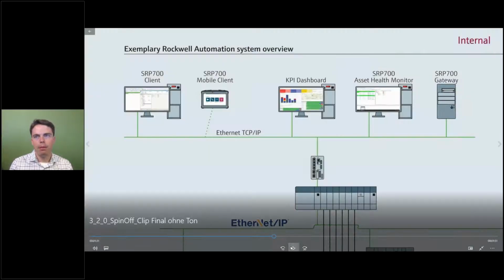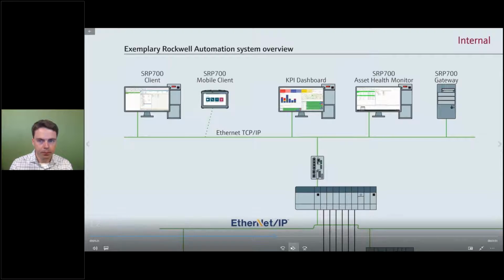The whole system is capable of handling up to 10,000 tags. Every gateway machine handles around 500 to 1,000 tags. It depends on how many tags are monitored, at what frequency, and on the hardware and software capability of that gateway. So it's really easily scalable. It works for small installations. We have a very attractive offering for small sites with 100 tags, really up to 5,000 or 6,000 or more tags per install. You can also combine different systems in case you have more than 10,000.